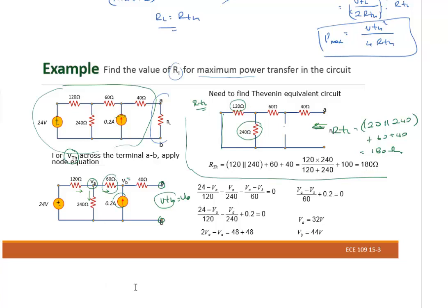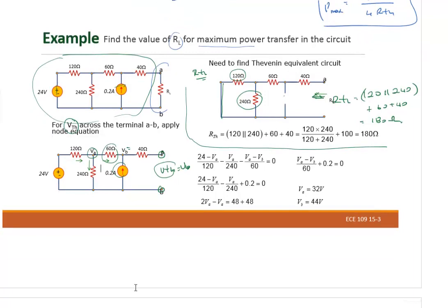In this case here, we said, okay, we're gonna write the node equation right there. If I call this one I1, this one I2, this one I3 here, I can say I1 minus I2 minus I3 equals 0. And you know I3 is equal to negative 0.2. We can put that one right there at the same time.